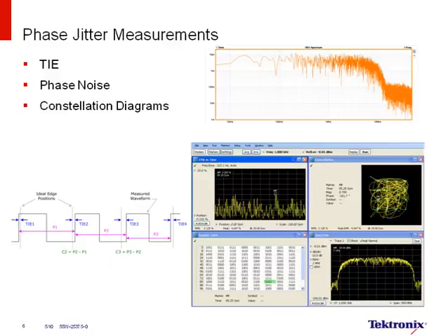That's one point. So that's how one thinks of phase noise. But I want you also to think about the entire shoulder, if you will, on the right side. Even though phase noise focuses on a specific offset, if you look carefully at the shoulder, there is a whole bunch of frequencies that live on the other side of this offset. All those frequencies exist even though the phase noise measurement only looks at a particular point.